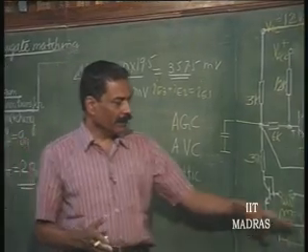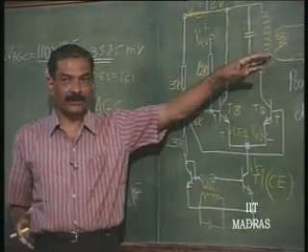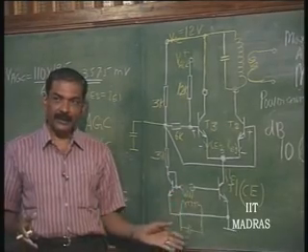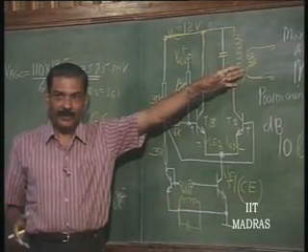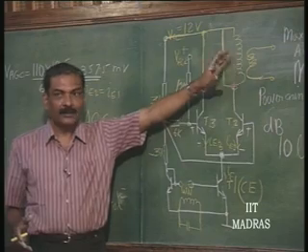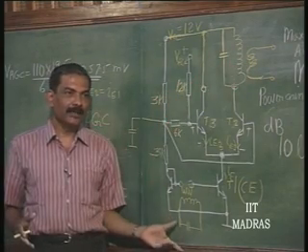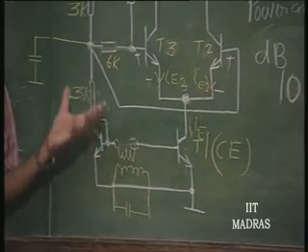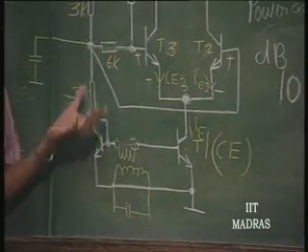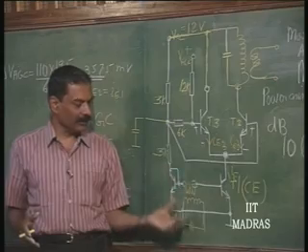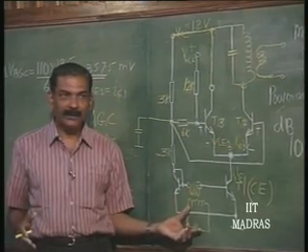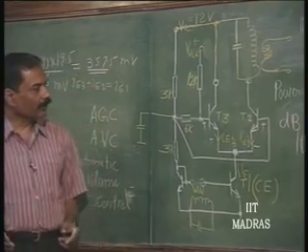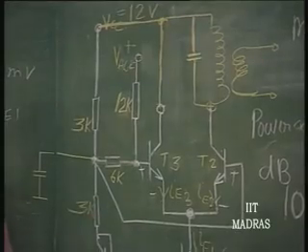So, correspondingly, a tuned circuit at the input and a tuned circuit at the output can be put. If it is an IF stage, this is IF and that is IF. If it is a mixer stage, this is IF, but this is a mixture of local oscillator frequency as well as the incoming frequency. The incoming frequency can be given here and the local oscillator frequency can be given here, because this acts as a multiplier or a modulator, and therefore, it is also used for a mixer.